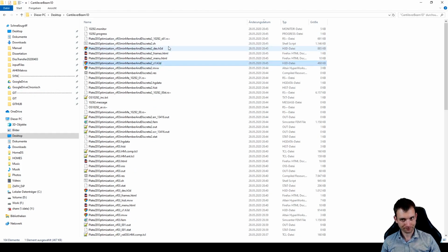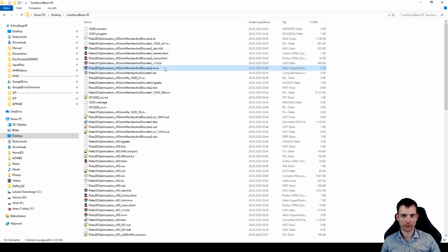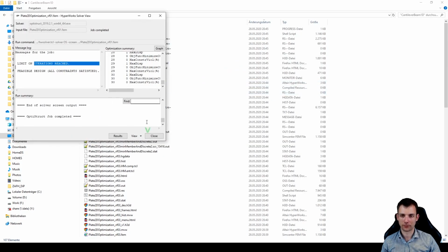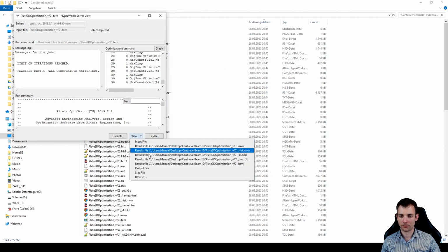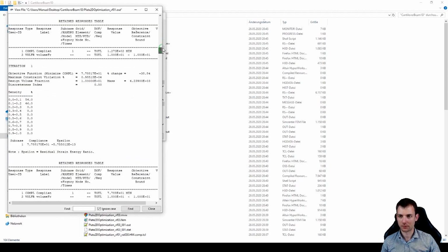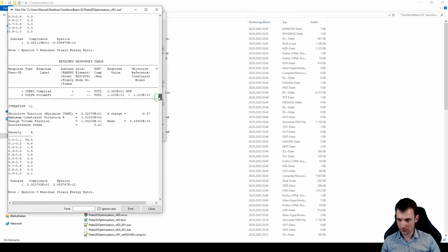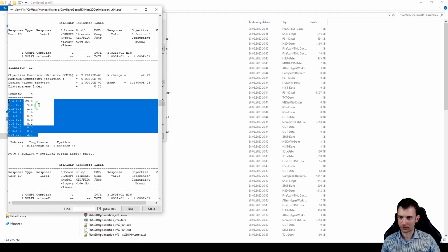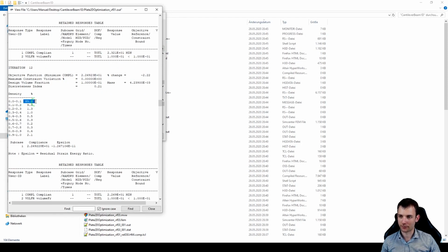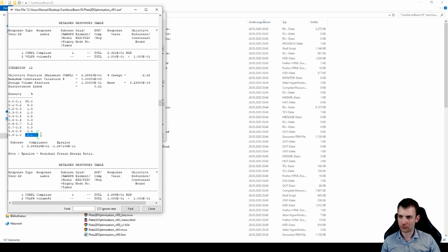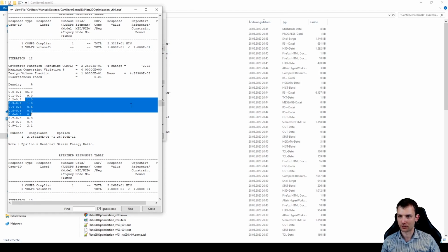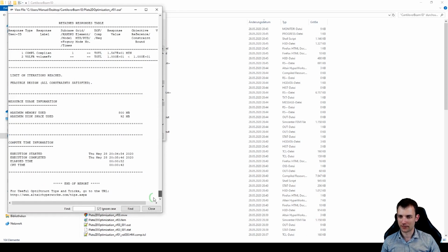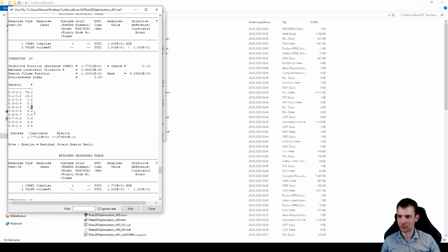So there's S1. Those are the two which are opened after the optimization. And then we also have the out file, which is basically the thing which is here, but a little bit more. So you see information about the different values of each iteration. So also the discreteness you could see here. 85% had a density between 0 and 0.1, and we have 2% here, and we have a little bit of middle density elements, and you can see that changing. It should disappear or become less and less, which is the case.